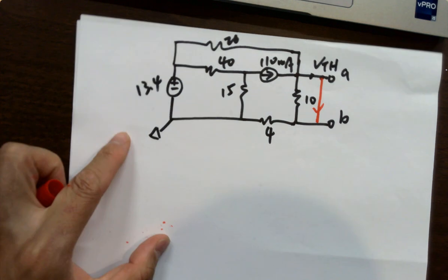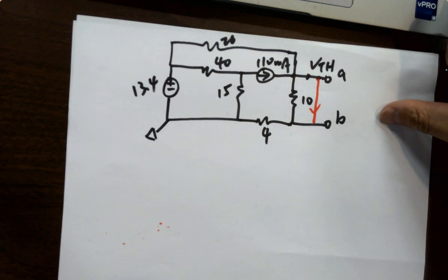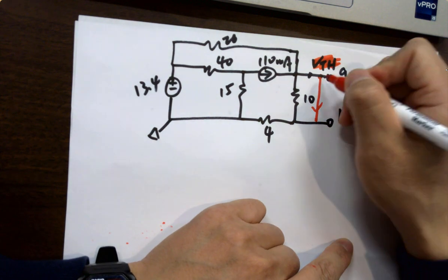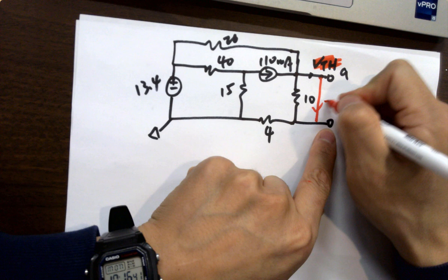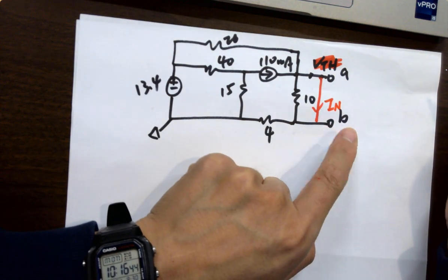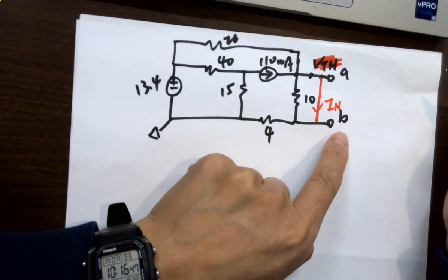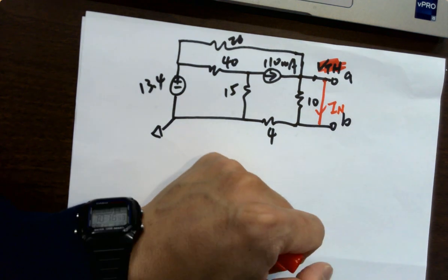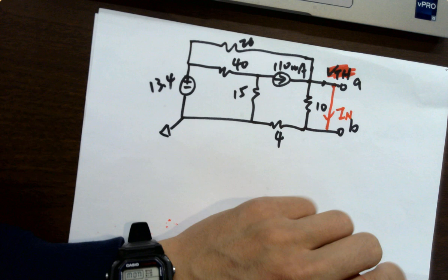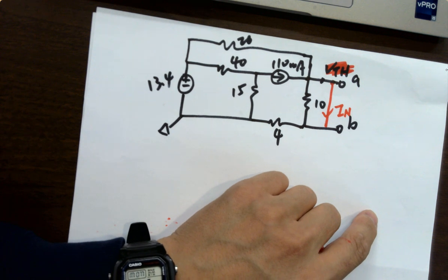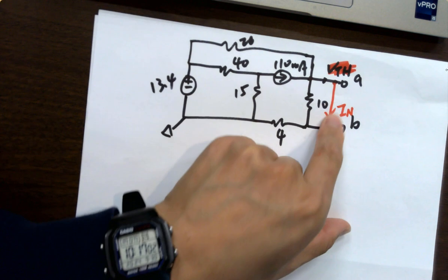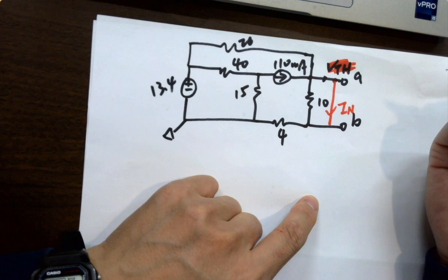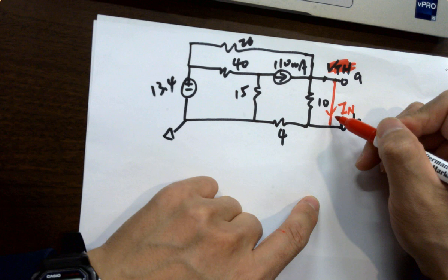However, if you are not converting to Thevenin first and are just trying to get IN directly, the way to do that is you connect the two terminals with a wire. Okay, that's the traditional standard way to do it. Keep that in mind. It will never give you any issues and errors. Directly draw a wire across it, and use whatever node voltage method or mesh or superposition you have to use to find out this current, and that will be IN.